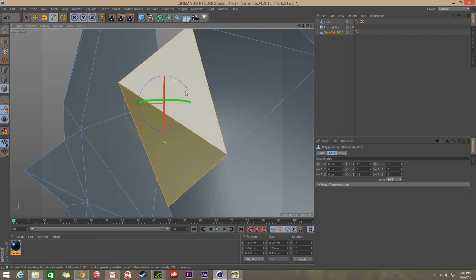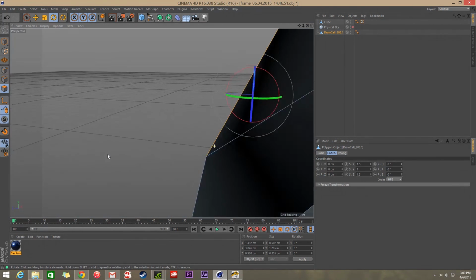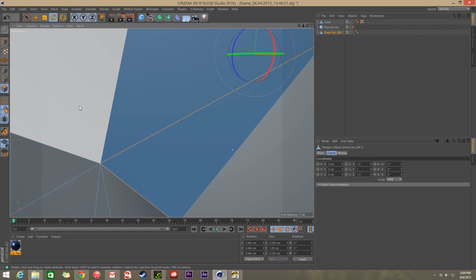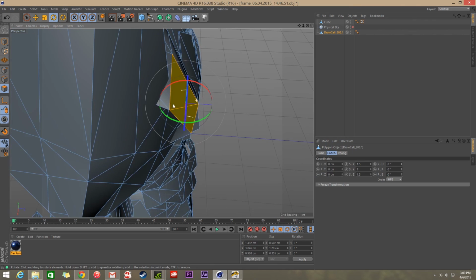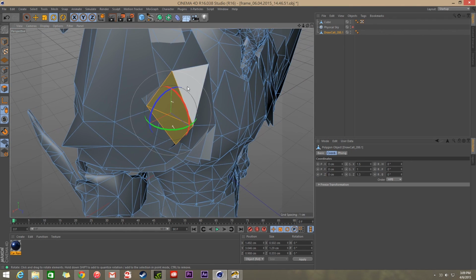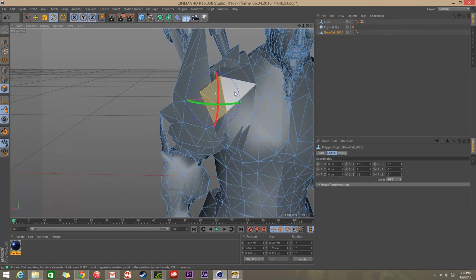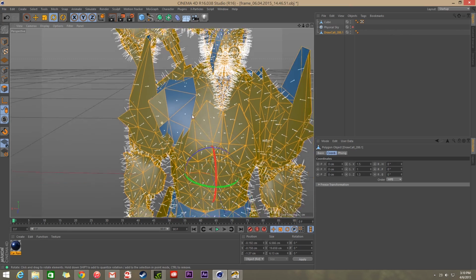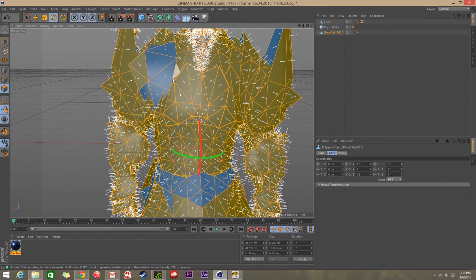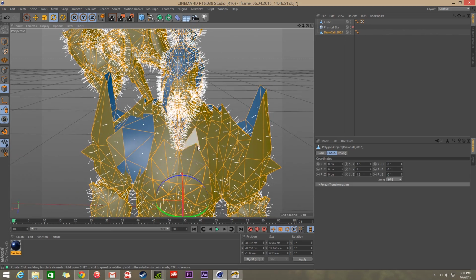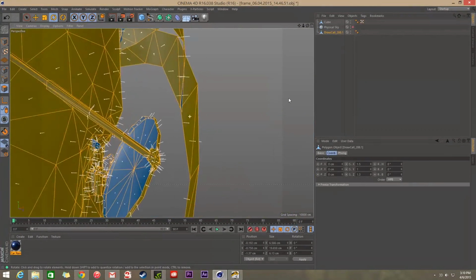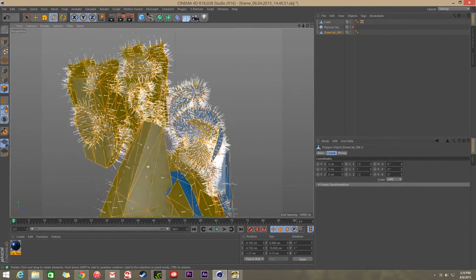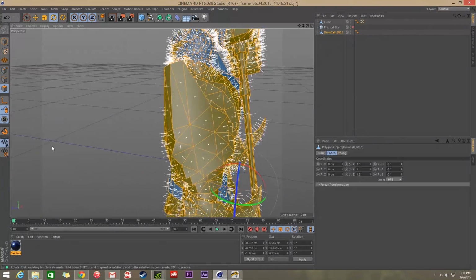That means that their normals have been reversed. I'm going to go inside right here quick so we can see that the blue is now on the inside, and that's the correct way. So it's all visually making the model fit how you'd like it to be. That's part of the process, fixing up his normals to make sure that he's matching like that. And I did a Control A so we can see the whole character. And now we see that there's actually a lot of problems. Like his hair through here is actually reversed. It should be the other way. This piece of hair, this part of his head. This shoulder actually came through nicely.